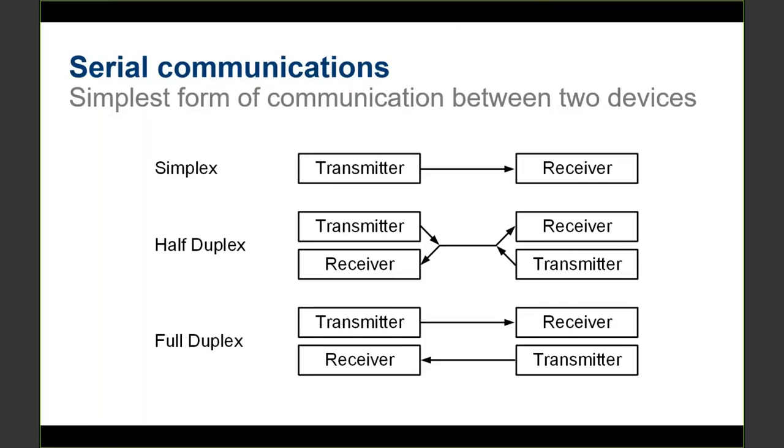So basically, with the switching, the turning on and off of these internal transmitters and receivers inside the devices, the timing becomes very important in a shared communications line like this, in this half duplex situation.